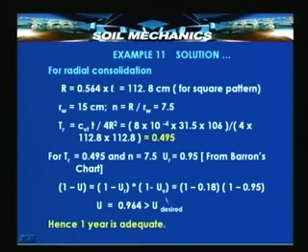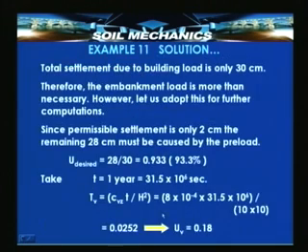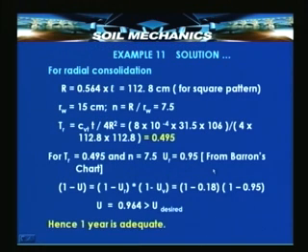What it means is, when UV is 0.18, corresponding UR is 0.95. That means the net U, total U is 1 minus this into 1 minus this, minus 1, that is 0.964, whereas what we needed was only 93.3%. So, this shows that if the preload is kept just for 1 year duration, we get 96.4% degree of consolidation. That means keeping the preload for 1 full year is sufficient to induce the 28 centimeters of settlement that we want.